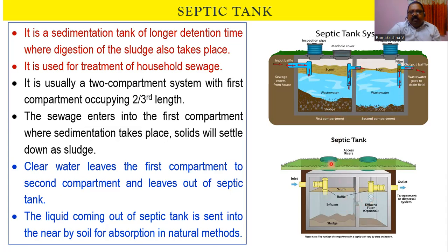And then we have manhole covers at the top, so that you can go for inspection in order to clean. You can take out the sludge for withdrawal at periodic intervals, and subsequently the septic tank can once again be put into operation.